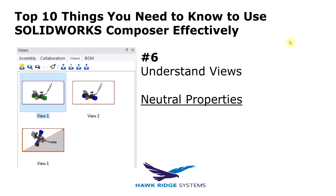Now, if I open it, I can choose for it to look back at SOLIDWORKS, and I just say File, Update, SOLIDWORKS Files. It updates and has all the latest changes. Now you just save that as a different file name, like RevB or whatever the next revision is. So you have your line-in-the-sand Composer document you can always go back to, and then your new Composer document that has those changes from SOLIDWORKS. So I hope that answered the question. If not, let me know, and I'll try to rephrase or figure out what exactly you're referring to.